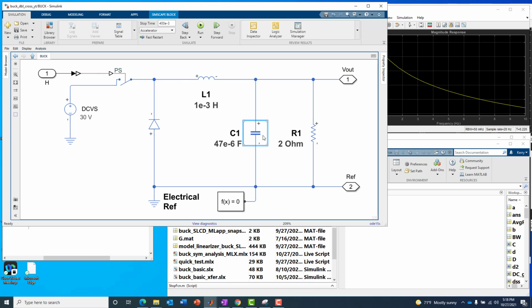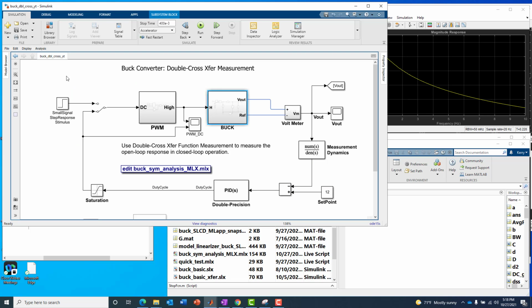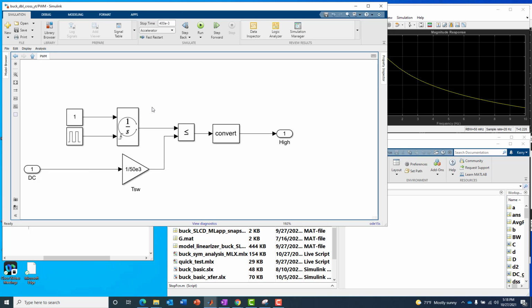We've got a basic buck converter circuit configuration, and we'll be driving this with a PWM signal. So essentially some type of pulsed on-off signal between, you could say, a 0 and a 1. And the only thing that's going to vary on that signal really is how long it stays high versus how long it stays low. It's so-called duty cycle. And that is modeled by this behavioral PWM subsystem where we have our clock driving a resettable integrator.